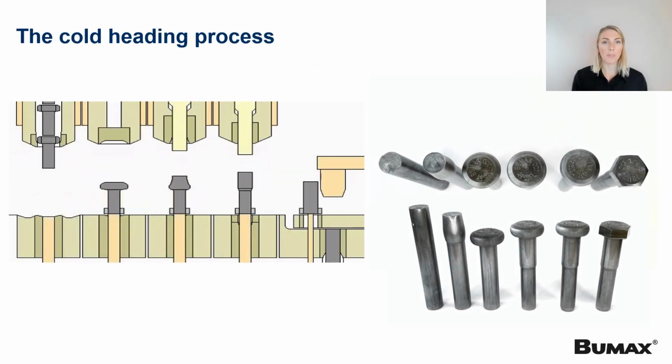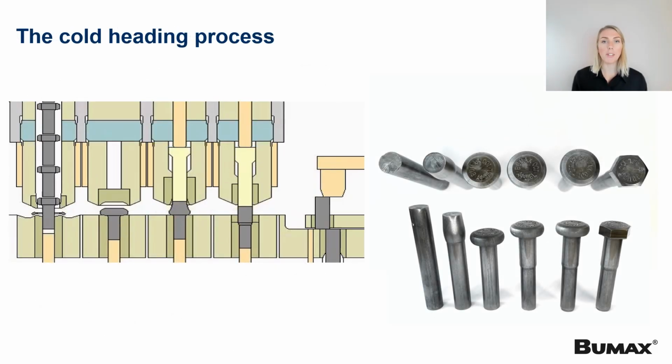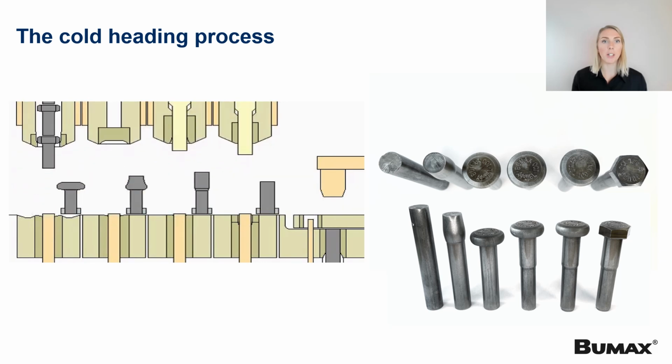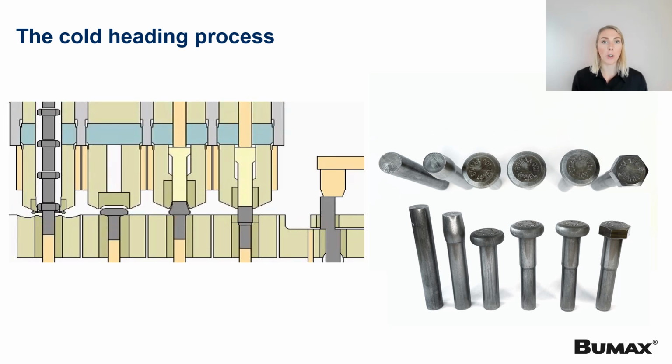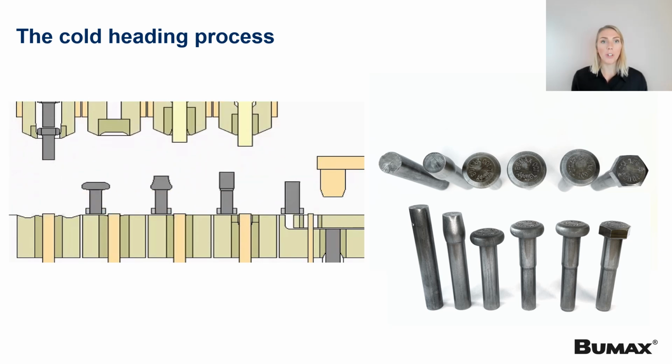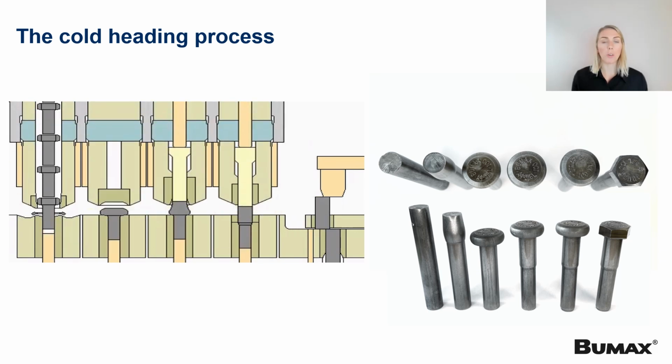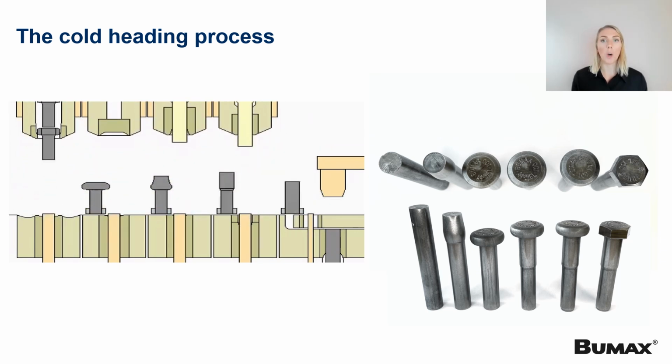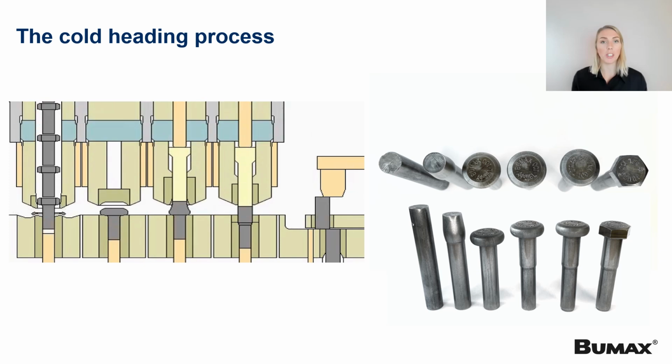Cold forging is a simple process where the workpiece is placed directly into the forging machine to instantly produce a finished part. Modern cold forming machines provide from 1 to 7 die stations, opposite a number of punches mounted into a slide.